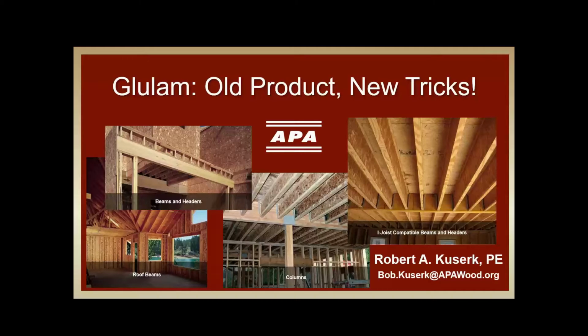But one of the significant developments in glulam really happened in 1942 with the introduction of fully water-resistant phenol resorcinol adhesives. This is what allowed glulam to be used in exposed exterior environments without concern of glue line degradation.